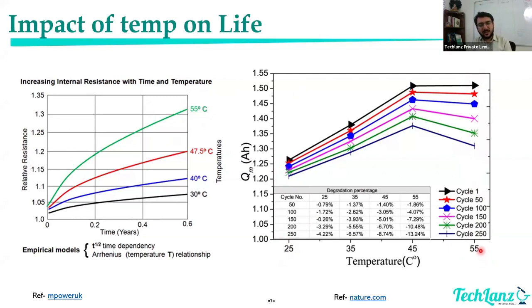So that means at any given point of time, if you want to operate at higher temperature, which is okay, it will give you higher capacity at that point of time. But over the period of years, side reactions will happen because of higher electrochemical reactions. Many side products get created, and electrolyte dissolution happens, because of which you get many byproducts in the chemical reaction. They create resistance inside the chemical paths, which increases the resistance and degrades the capacity over time, right? This is something very important.